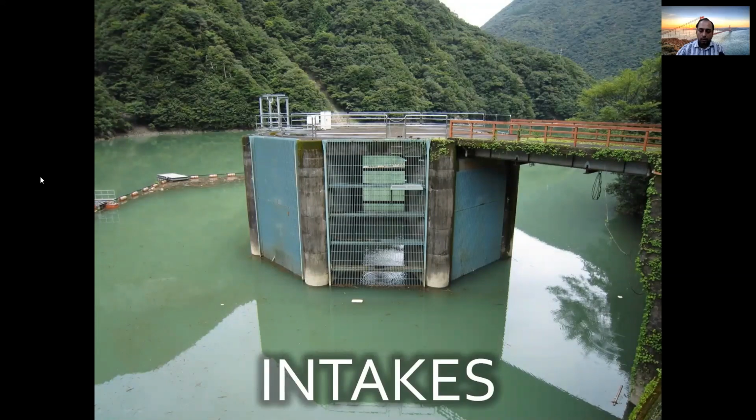So let us discuss a little about the intakes. What are its roles, what are its components, and what are the design aspects. So the first role of this intake, it's a very small component, but very important, because it prevents the entry of trash in the system, in the water conductor system. Trash is very damaging because that will cause blockage, erosion of turbines and so on. But more importantly, it can cause blockage because you may have small openings at turbines or in the spiders or in the governors, and there these small openings can be blocked by floating debris. So these intake structure will prevent the entry of these floating.